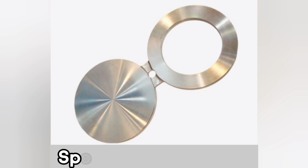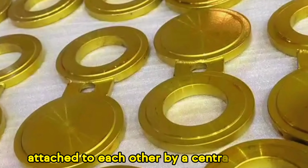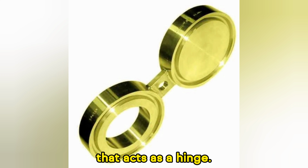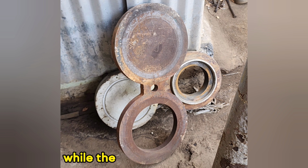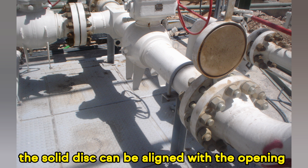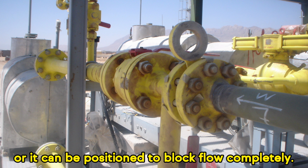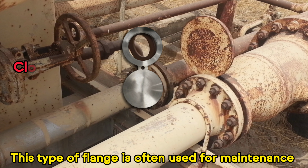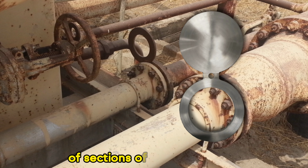Number 2. Spectacle blind flange. A spectacle blind flange consists of two metal discs attached to each other by a central section that acts as a hinge. One of the discs is solid, similar to a standard blind flange, while the other has an opening. By rotating the spectacle blind flange, the solid disc can be aligned with the opening to allow flow through the pipe, or it can be positioned to block flow completely. This type of flange is often used for maintenance or shutdown purposes, allowing easy isolation of sections of piping systems.